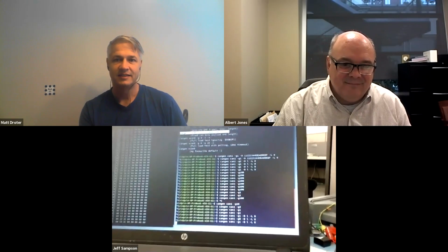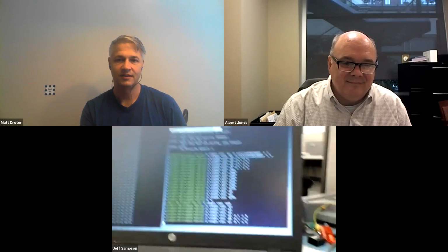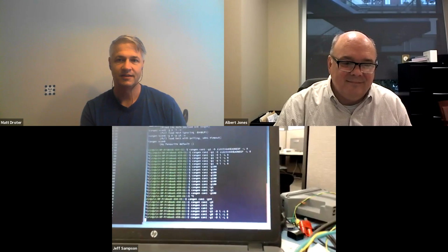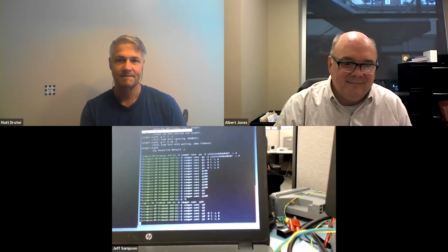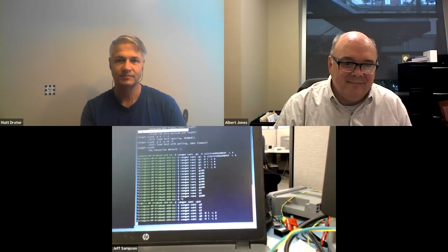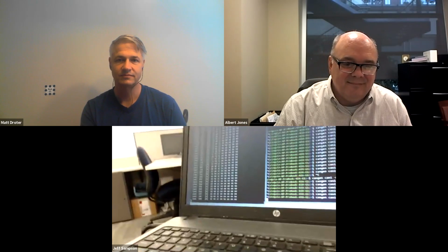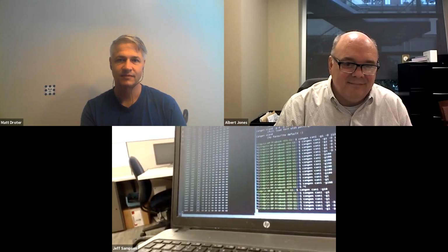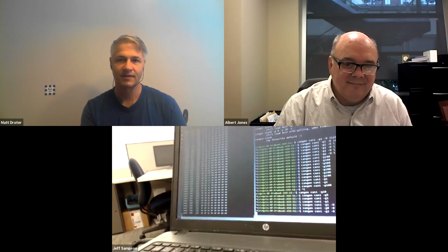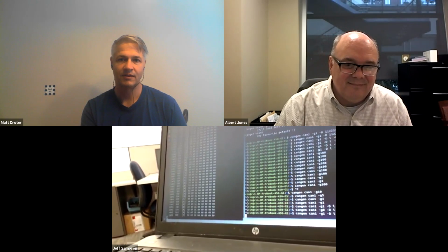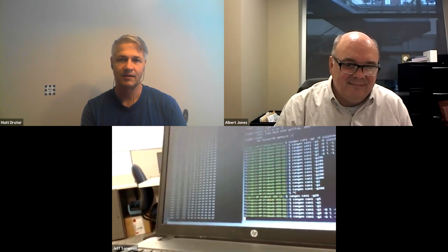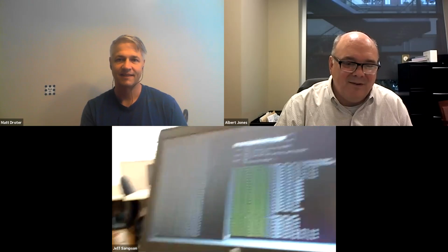this is the Linux side that's talking to this little adapter right here, and the Linux side is generating this message and the -g1 that's in there says put a 1 millisecond delay after each one, and over here is the messages that says the CAN dump. So the ones generating them is coming back out. And according to the number, which you can't see, the fourth column is an 04, which means I've sent 64 million packets since yesterday afternoon with the thing, and it hasn't locked up.